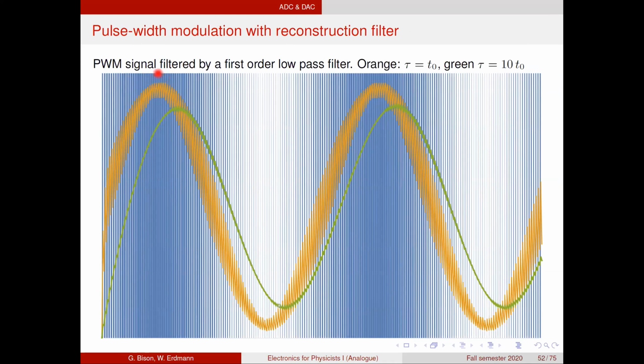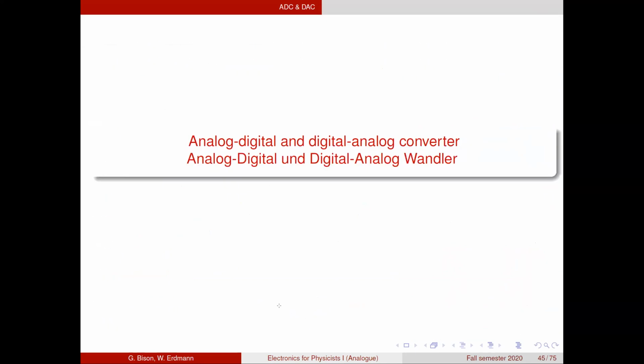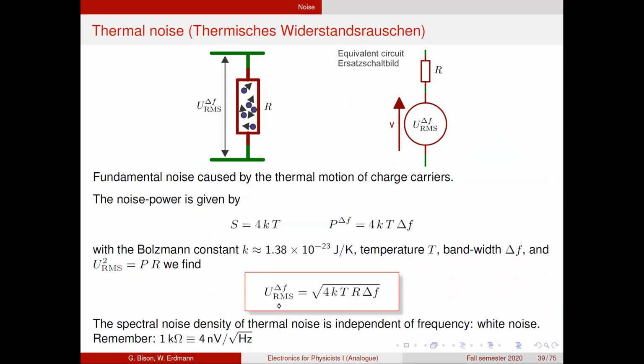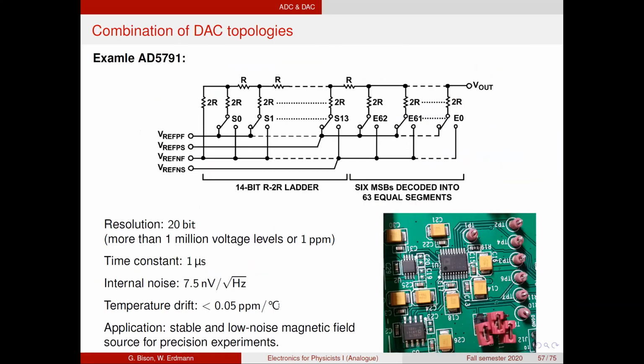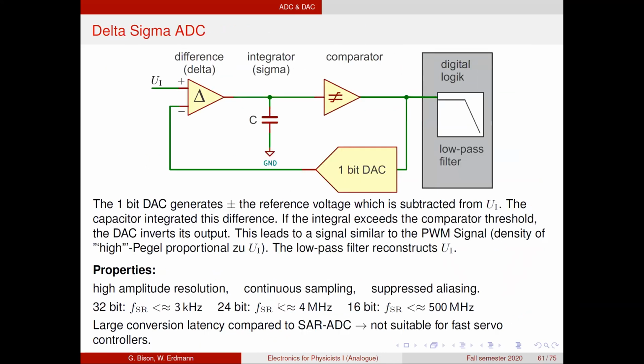And you see already here we have the high density of pulses, but the filter gets to a high value only here, so there has to be a certain time delay. This makes it typically not suitable for fast feedback, for example. So the time it takes, the latency, the time it takes that the digital logic here is aware of a signal change can be substantial.